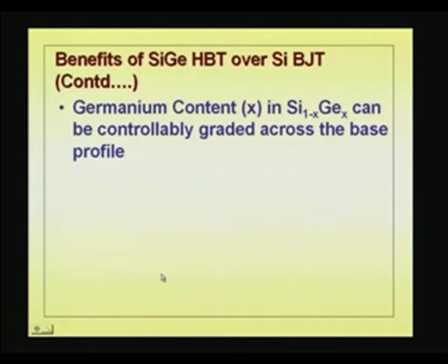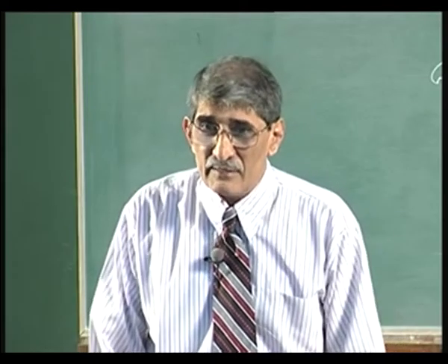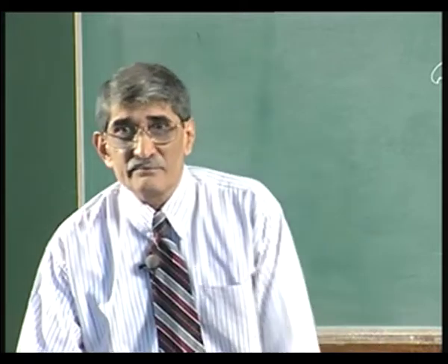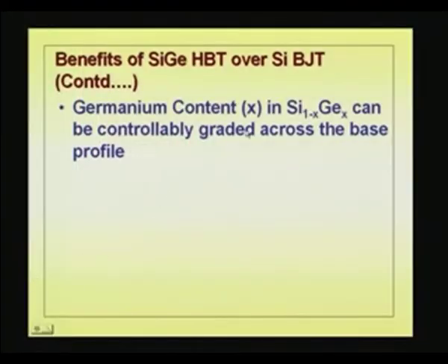Another very important advantage which is there for all the HBTs, but mainly exploited in the case of HBT silicon germanium transistors is this factor. Germanium content X in silicon germanium can be controllably graded across the base. I do not know whether it rings the bell.